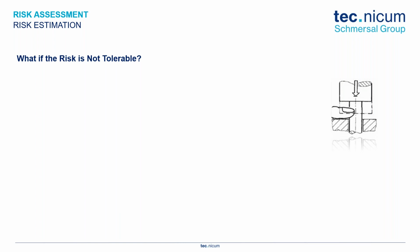We look at the machine, we see some motions, and we ask, what is the potential source of harm? That moving cylinder. What's the risk associated with that? Part of the risk is, what's the harm? There could be some crushing there. The other element of a risk is the probability and likelihood of occurrence. We'll look into that.